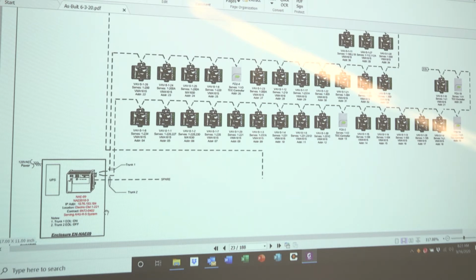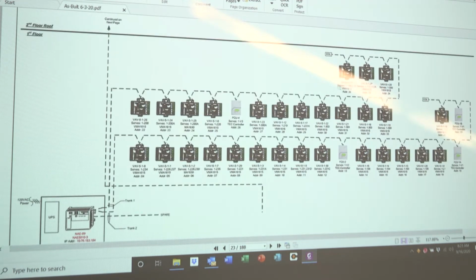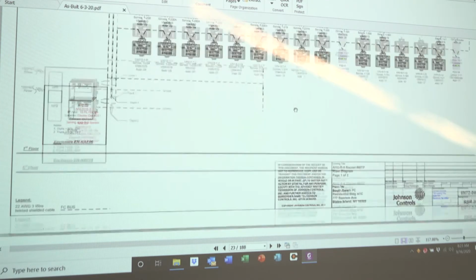Everything is exposed in electrical rooms. You're not above ceilings looking at these panels. Air handler 5 runs through VAVs. Okay, picks up a couple of fan coil units. These are your main entrance, 1A, 1B, stair towers and corridors. Okay, running through all the VAVs, a daisy chain.